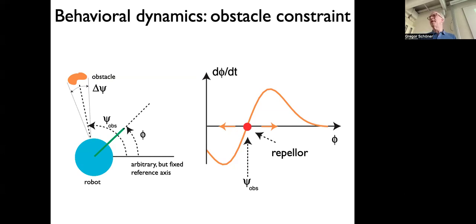There's a little bit of a cheat I often do in these lectures, in that the mathematical convention for angles is that they are positive counterclockwise. And in our papers, we did that. We turn to the left, and these angles grow. Well, it's conventional to plot these dynamical systems always with the variable to the right. Just also a convention. And that means that when you're going to the right here, the robot turns to the left.